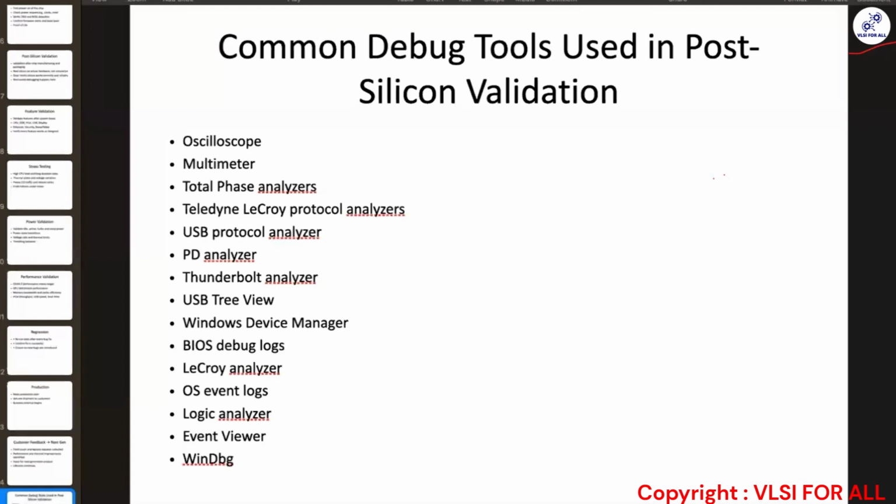And BIOS debug logs. These are serial logs you will capture. Consider you are not able to boot your system. It is booting, but it is not reaching the OS phase. So you may have to capture the BIOS log. You connect your serial cable to your reference board.